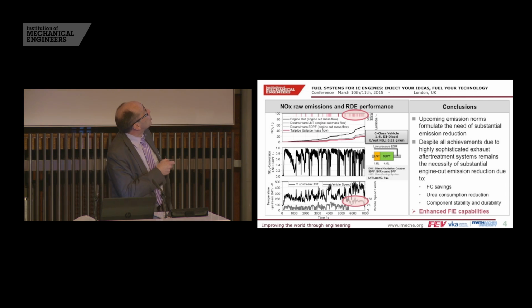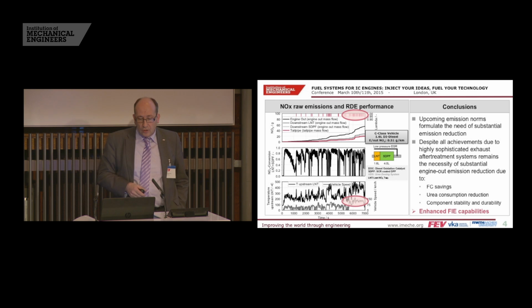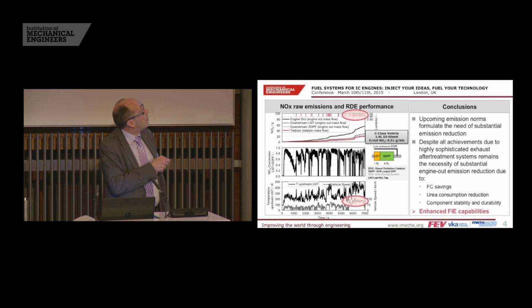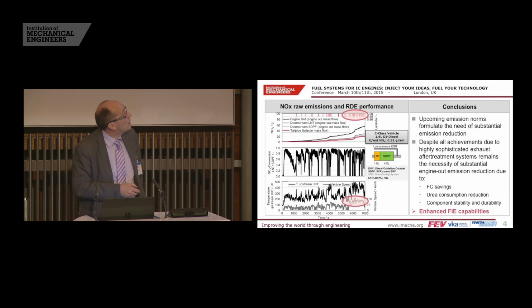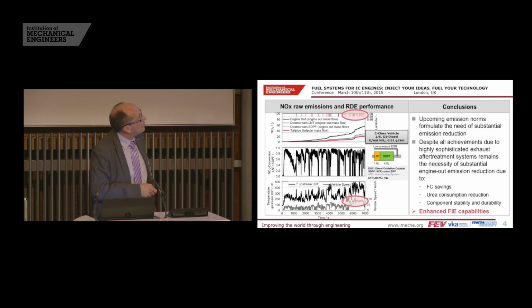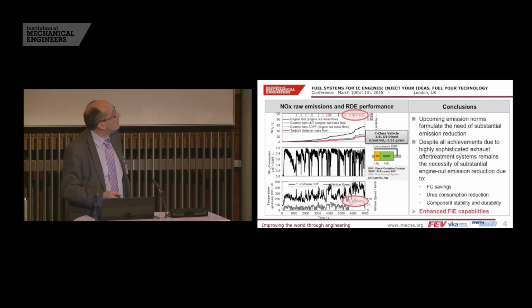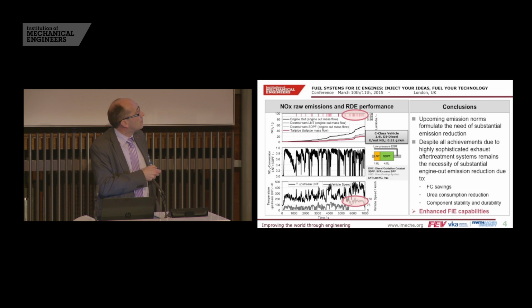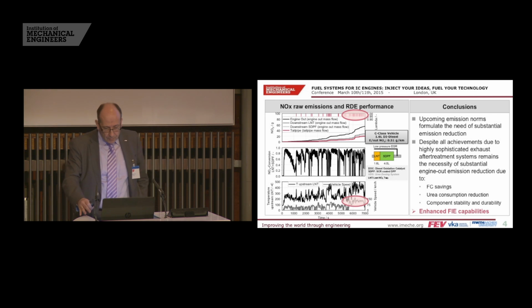In the upper chart, you see the evolution of the NOx emissions as a function of time, subdivided between engine out and several states along the exhaust system. This is a representative example for a compact or mid-sized car, which we currently consider a very challenging situation, because under current conditions these vehicles are mostly equipped with LNT technology.